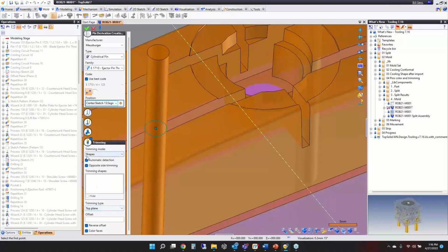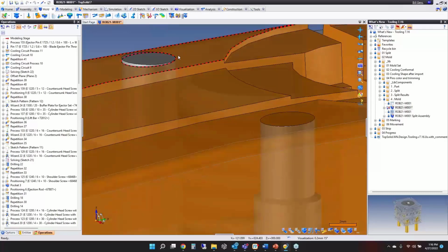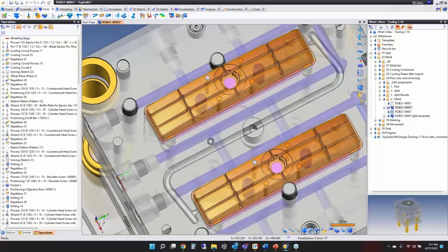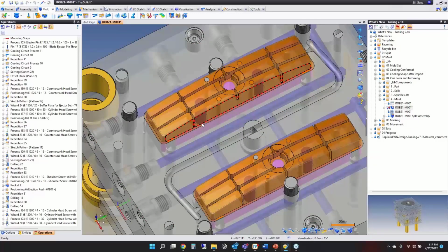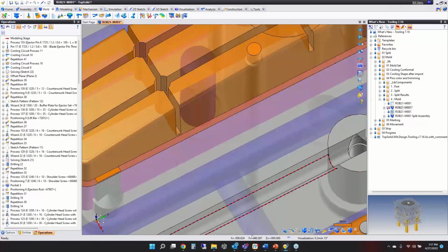Oh, that's what I did, okay. So we want to be on shapes. You trim to the top plane. Then what happens is because it's not being trimmed by this detail, it's to the highest Z detail and making it a planar trim, the coloring stays uncolored because it's not matching anything, okay? And if an ejector pin was passing through, let's say molding detail and shutoff detail, then it would be both colors across there.